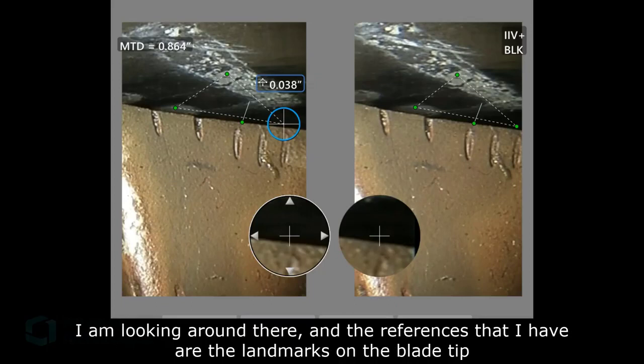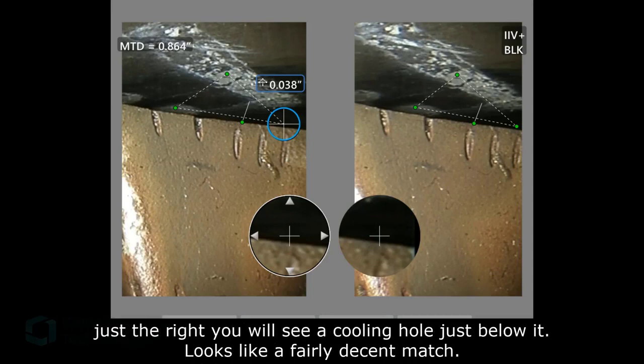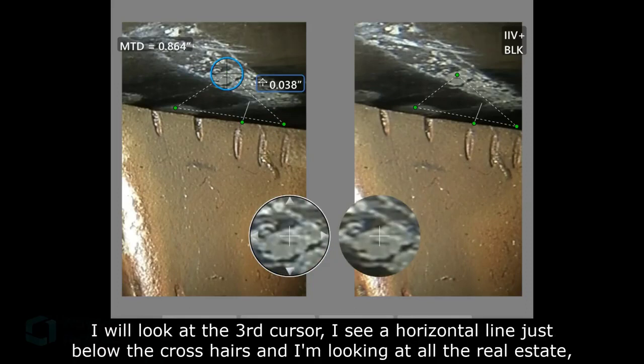I'm looking around there, and the references that I have are the landmarks on the blade tip just below the crosshair. You'll see some rises just to the right. You'll see a cooling hole just below it. Looks like a fairly decent match. I'll look at the third cursor.